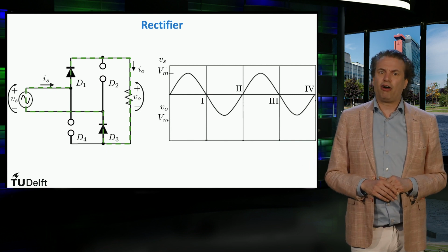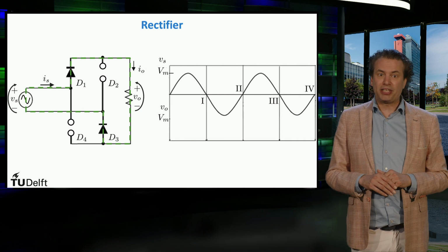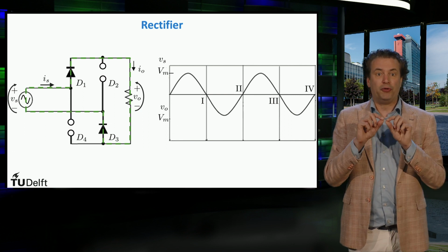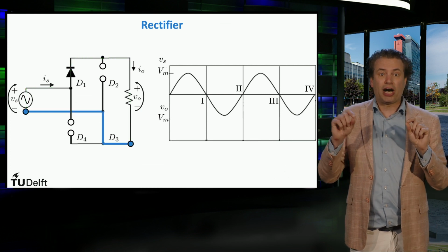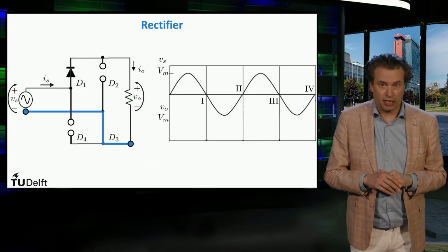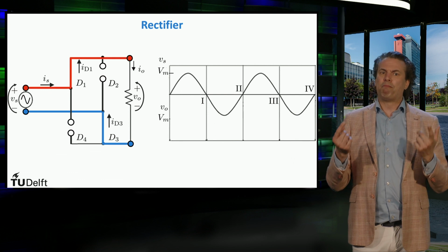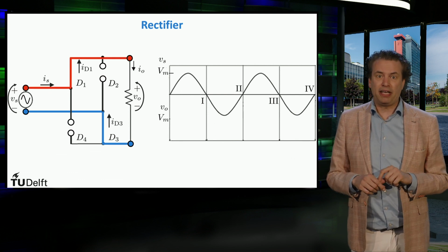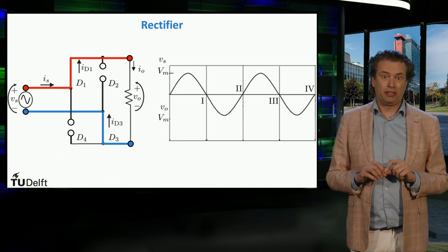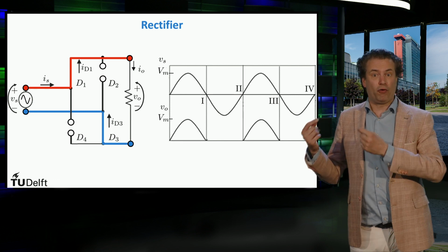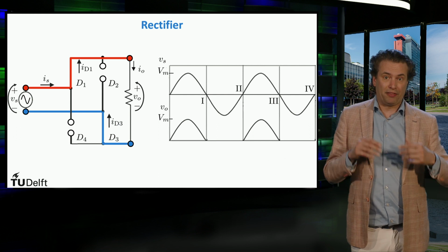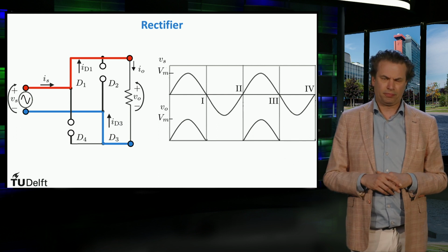Notice that the direction of the arrow in both the input and the output voltage goes from the node highlighted in blue, the negative side, to the node highlighted in red, positive side. This means that both voltages are the same in magnitude and direction, therefore the output voltage is the same as the input voltage in the time periods 1 and 3 as shown in the figure.